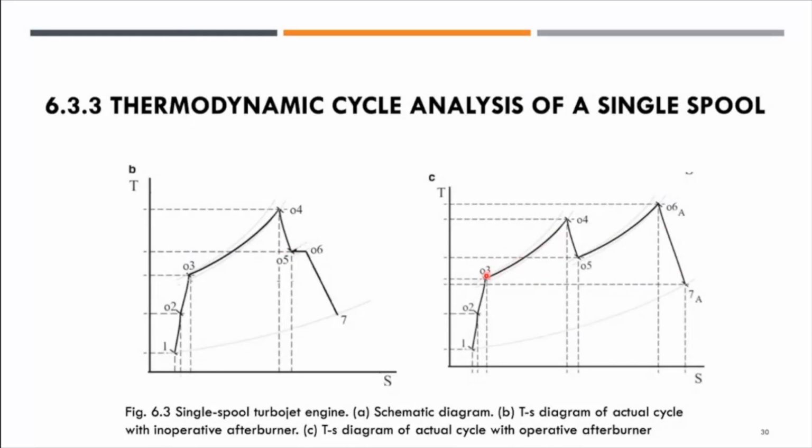You can see that the temperature has already risen in the combustion chamber as it goes to the turbine stage. Then there is another step of temperature rise when the fuel is injected again, so there is an afterburner process over here.